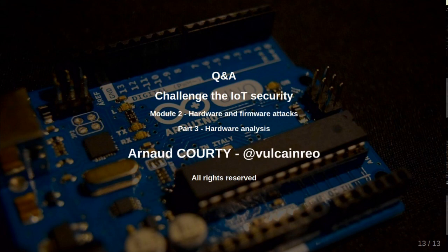Conclusion. In this module, you have discovered how to get information about pins and, more precisely, try to be connected to an unknown UART port. Remember, communication port design: UART equals 4 pins, SPI is labeled MOSI and MISO, and I2C is labeled like SDA or SCK. Thank you.